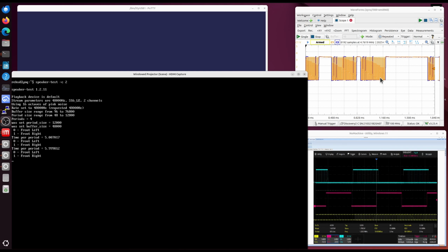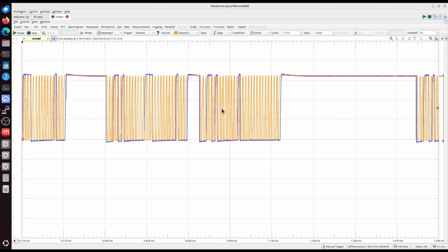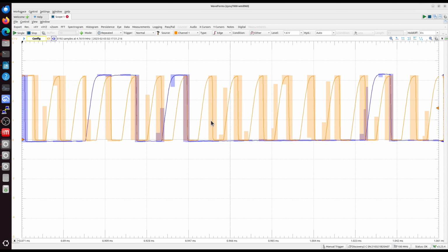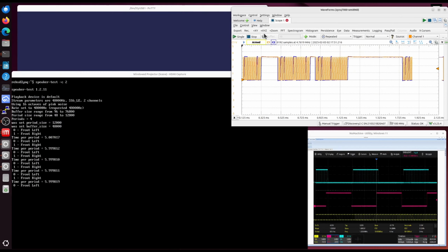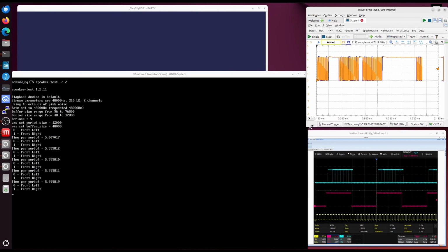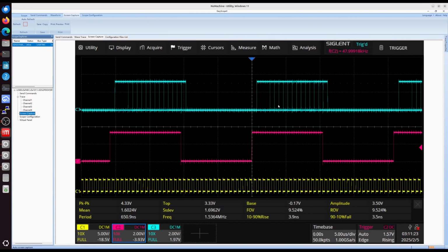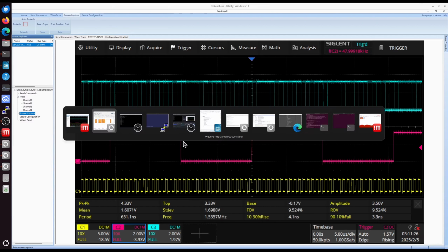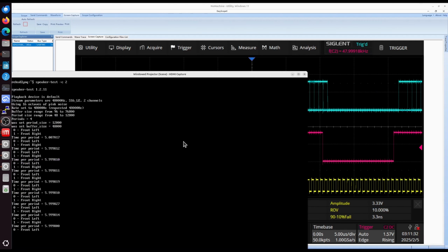Now, what I'm seeing up here as I did that, I saw the I2C signals, and I can zoom into that and see both my clock, the orangish color, and the data superimposed on it. So if you see activity happening here, it's the I2C control that it's working with. Then I can also come in here and look at this machine, and I have the clocks and the data that I can look at as it's doing this. So I might get over here and just break out of that.